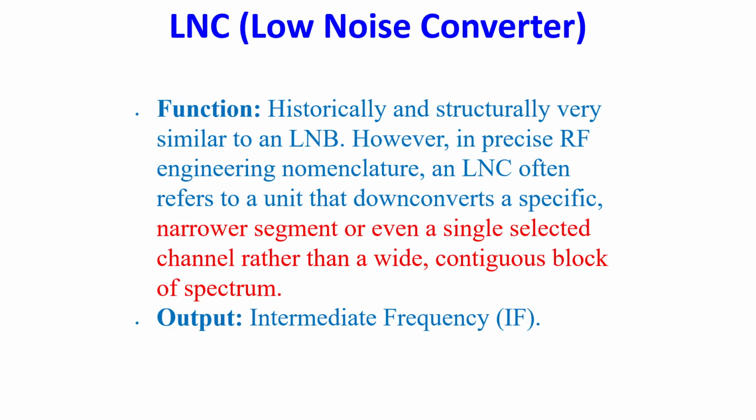LNC, low noise converter. It is an LNA and a frequency converter stage, historically and structurally very similar to an LNB. However, in precise RF engineering nomenclature, an LNC often refers to a unit that down converts a specific narrower segment or even a single selected channel rather than a wide contiguous block of spectrum.